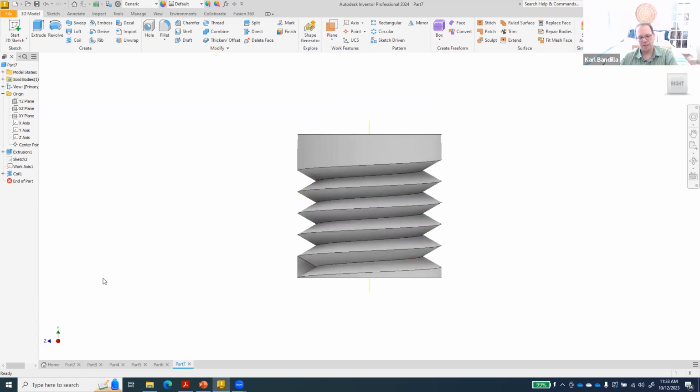Right now, remember that of course we don't want to have these very sharp corners up here and down there at the crest and the root, because those are failure points. So if we want to create this correctly, then we wouldn't want to cut out a triangle. We would want to cut out either round edges with a triangle or something else. But in general, we can create these relatively simple. So if we want to show that this is a thread, this might actually be a better way of doing it, because it's not that difficult to do. It took us maybe 5 minutes to create this, so overall, I think that's not too bad.